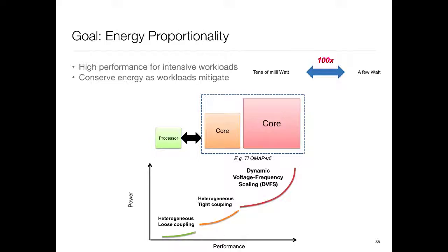TI, for example, has processors where they take this big.LITTLE, and then they also attach a totally separate processor of a different instruction set architecture. So the idea could be that this little processor, which is extremely efficient, is normally the only one which is up, everything else is asleep, waiting for things to happen in the world, and when things happen, maybe it examines them, sees if there is something interesting, and if so, it wakes up the main thing.